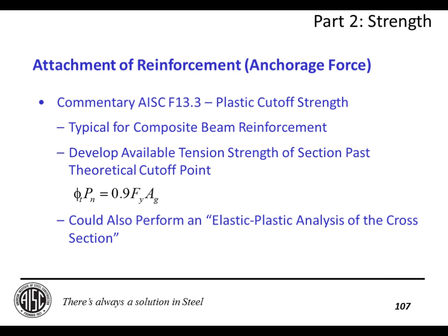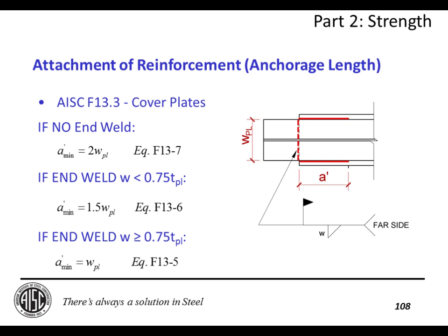For plastic strength, the cutoff is simply the full strength of the member that you are adding. So phi Fy Ag. This is what I normally do. You could also perform an elastic plastic analysis to see how much stress actually is crossing that cutoff point with your plastic model. That's as complicated as it sounds, so generally I stick with 0.9 Fy Ag.